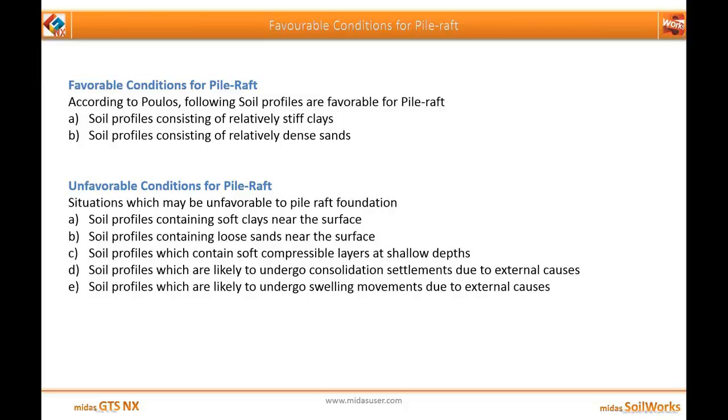The unfavorable conditions for the pile raft are, first two, if you can see, soil profiles containing soft clays near the surface or loose sands near the surface; there pile rafts are not recommended.